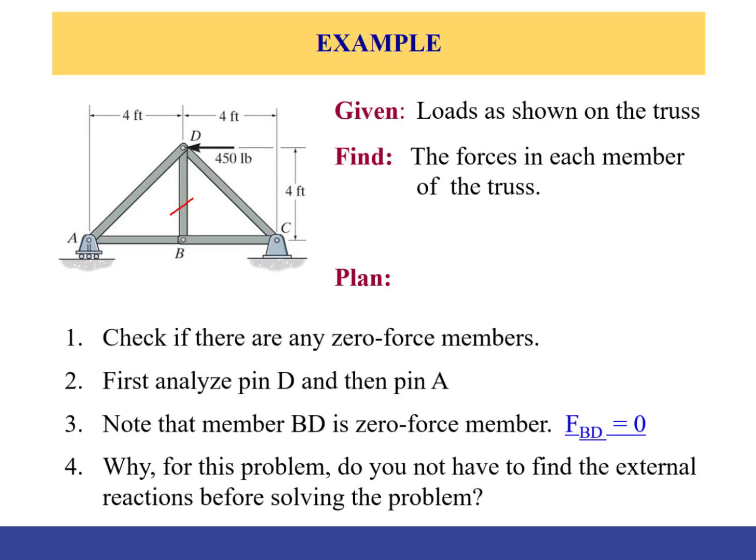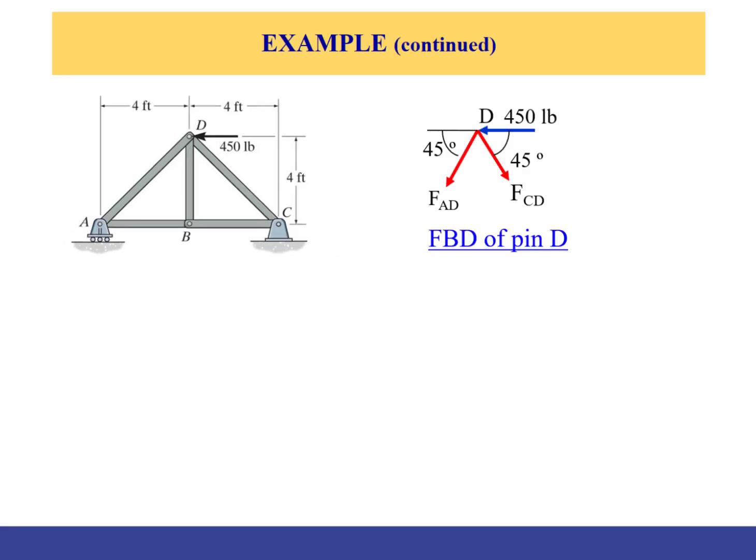So in summary, these are the steps. We'll start with drawing the free body diagram at joint D. So assuming this is in tension, right? Tension, meaning that the force is pulling on AD, therefore D is experiencing some force equal in magnitude, opposite in direction, so it's going down, right?